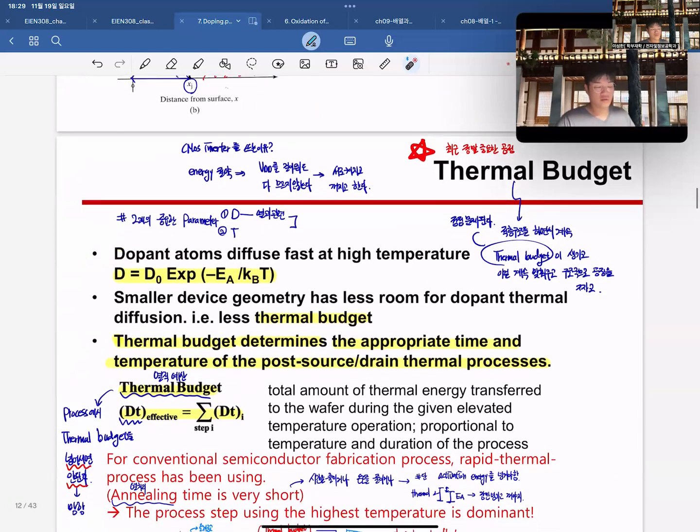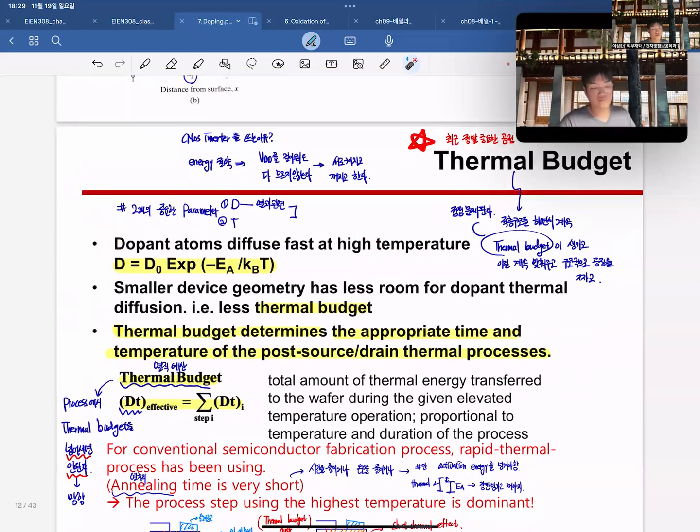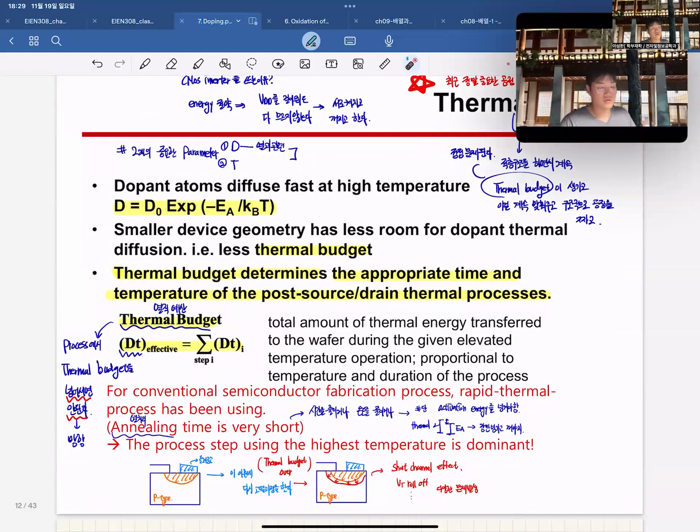The thermal budget is the first consideration. If we look at step 1 and step 2, step 1 is done at under 800 degrees, and the second step needs 1000 degrees. This can cause breakdown before we can reproduce it. So the thermal budget is very important to the whole process, and we evaluate other processing by considering their thermal budget.